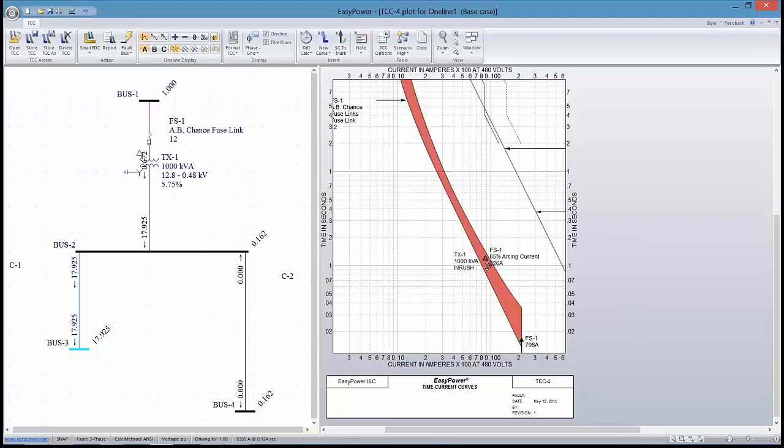The significance here is the 85% versus the maximum current for that bus. The reason for that specific calculation is a requirement of IEEE to take the worst case between 100% and 85% and compare them for tripping time.